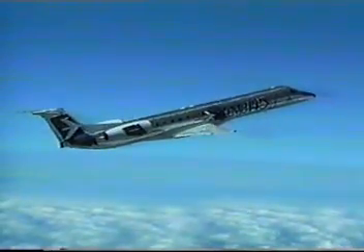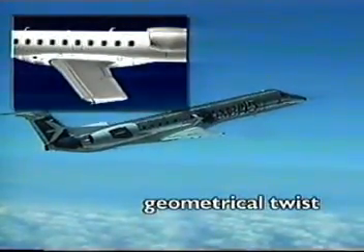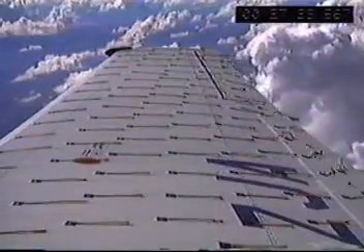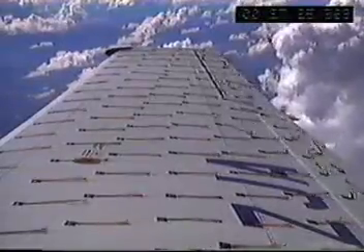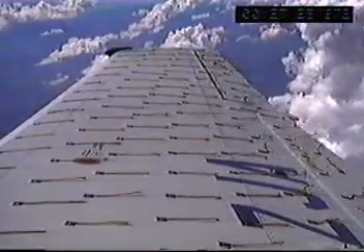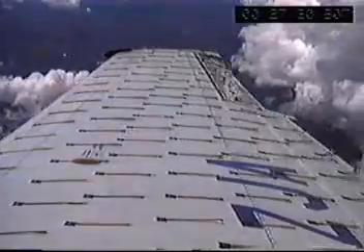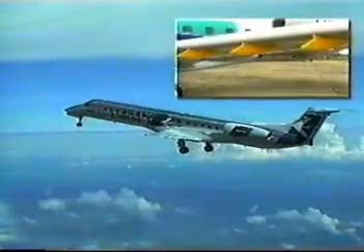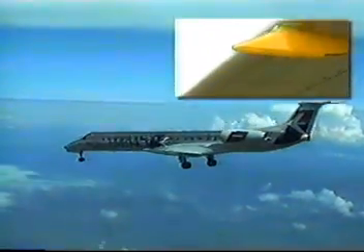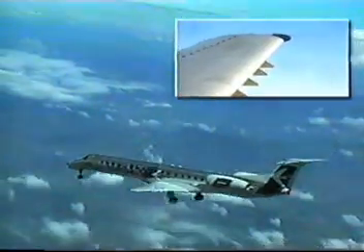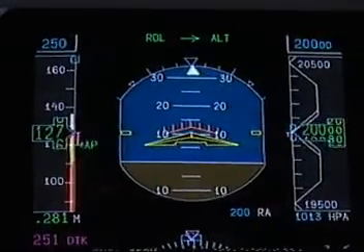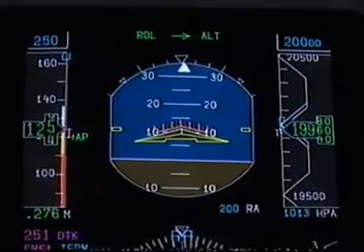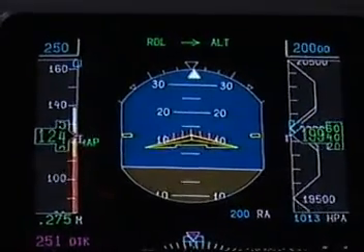There are several means of correcting the tip stall tendency. The Embraer jets make use of wing geometrical twist to decrease the local angle of attack at the tip. In addition, the airfoil section is varied throughout the span to an airfoil with delayed stall development. Another feature used in the Embraer jet family are those interesting vortilons installed at the wing tip. They delay tip stall even more, so the jets have full roll control throughout the normal operating range down to stick pusher speeds.